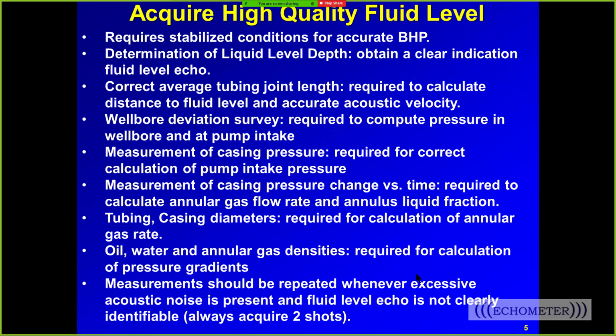If you read John's paper, he'll talk about it a little bit more. But basically what we see is that the liquid level in the tubing and casing are about the same, and when you pump the well, the fluid level won't move up in the tubing because it's leaking out the hole. And so you can't see below liquid level. You can only see above the liquid level because the pressure wave won't travel in the tubing below liquid.